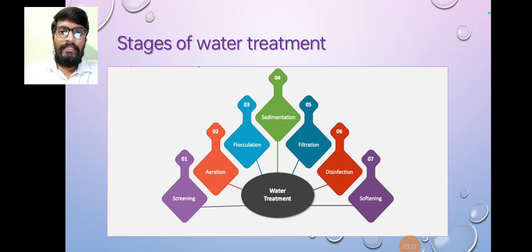The next stage is screening. After screening, the next stage is aeration. After aeration, the next stage is flocculation. After flocculation, the next stage is sedimentation. After sedimentation, the filtration process is there, and after filtration, the disinfection process. After disinfection, the softening process.